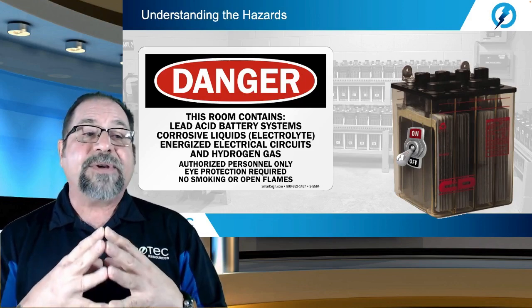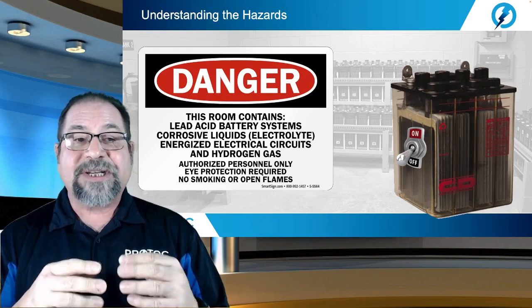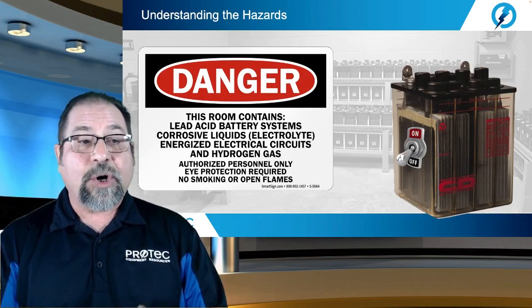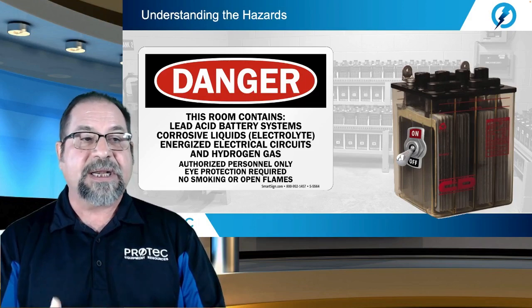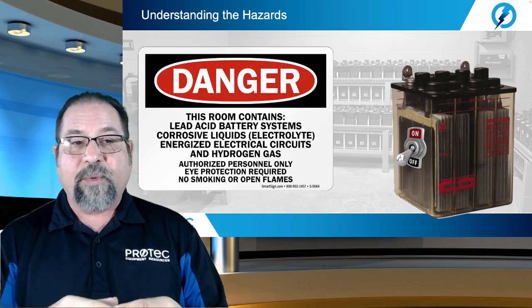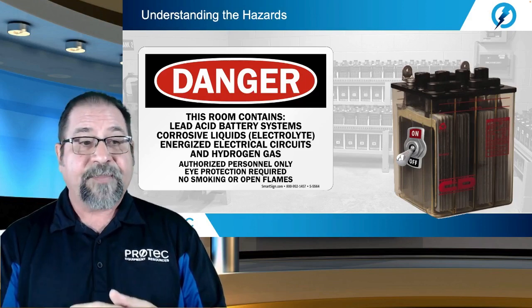Now, since a battery stores charge, when a battery is charged, it cannot be turned off. Even with the battery charger turned off or removed, the battery bank will store charge until it is discharged. Therefore, when working in a battery room, we are working around energized equipment.